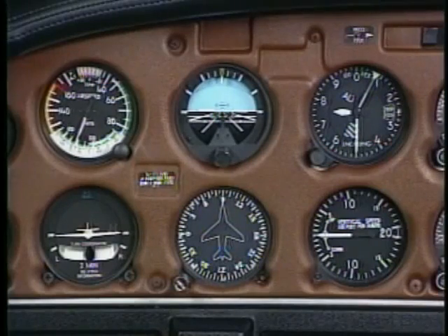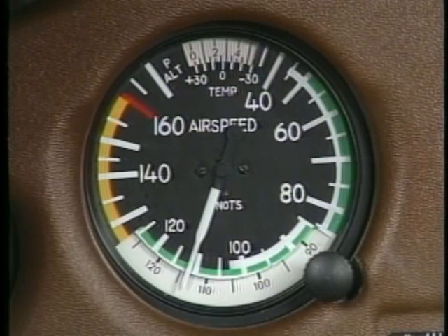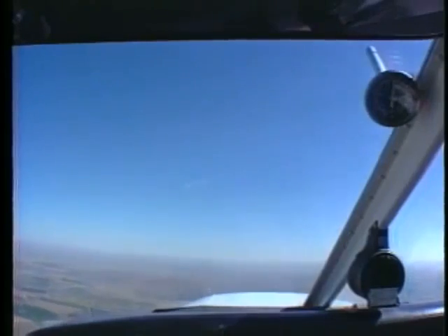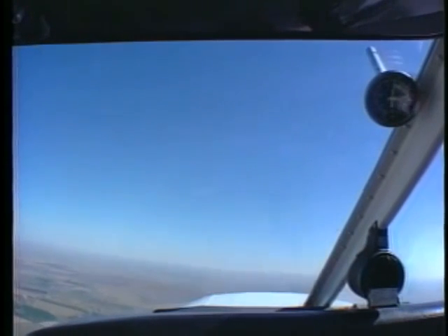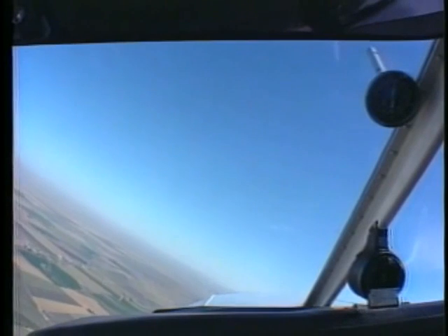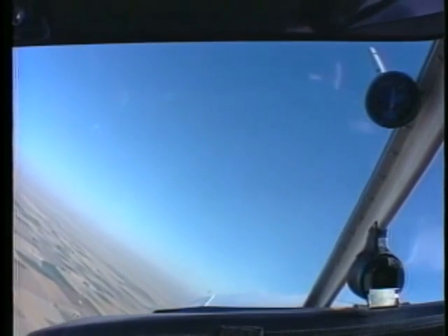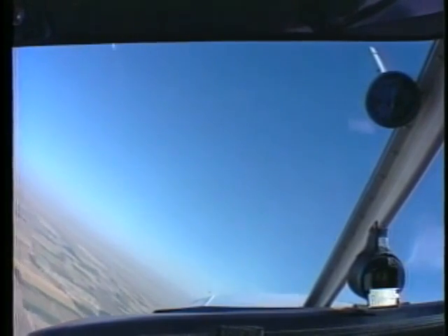Part of your preparation includes configuring the airplane at its maneuvering speed or the recommended entry speed. By remaining at or below this speed, you should not exceed the limit load factor. Once this is established, begin the maneuver by smoothly rolling into a 30-degree coordinated bank. Then apply control wheel back pressure to increase your pitch attitude and add full power.